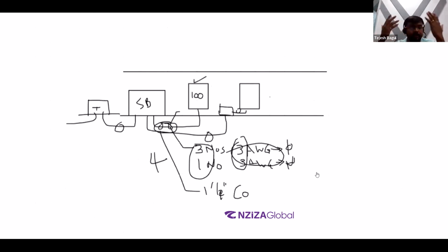All right. But when we are talking about, let's say, the outlet, right? The other day we spoke about the receptacles being 16 amperes as a standard in Rwanda. So for 16 amperes, you don't need to mention each and every wire size, each and every conduit size, because that outlet is going to have 2 or 3 wires, one for phase, one for neutral, and one for ground.